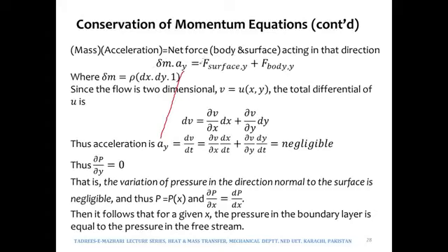While considering the surface forces, because we are not considering the body forces, in the case of surface forces it would be only the pressure, right? Dou P by dou Y on the right hand side of the equation, as we had written for the surface forces in x direction. There were two terms on the right hand side while we were writing the surface forces in x direction. So therefore dou P by dou Y would become equal to 0.